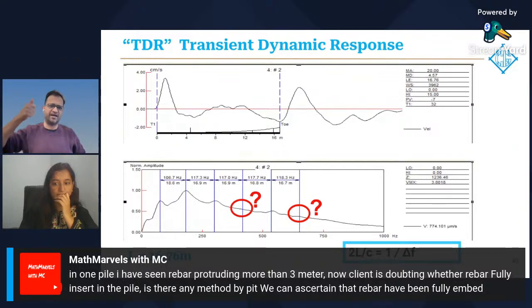Your piling guys, supervisors, operators and labor have to know what they're doing. Good, normal practices for pile construction, like cleaning and flushing the pile bottom, trimming, concreting, and making sure your cage goes all the way down to the bottom, cannot be replaced just because we're doing testing.